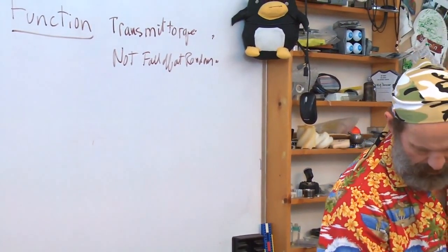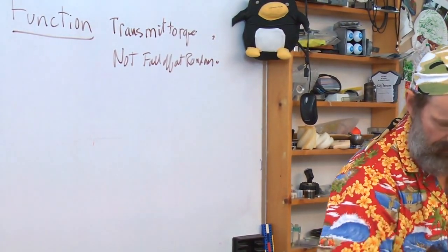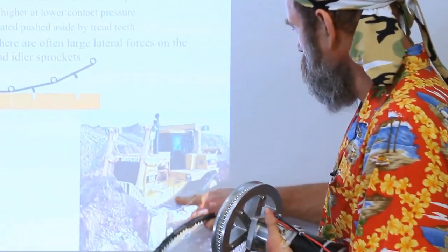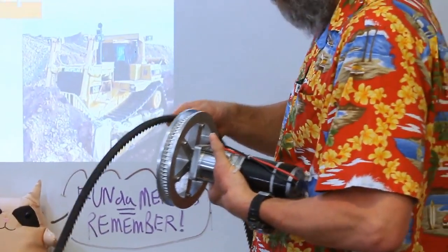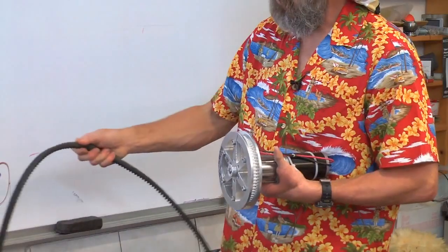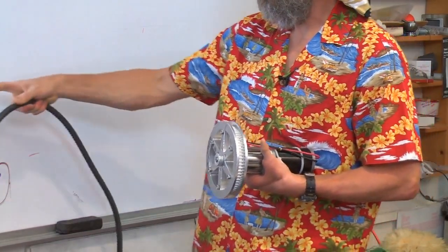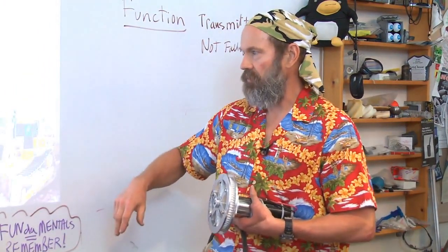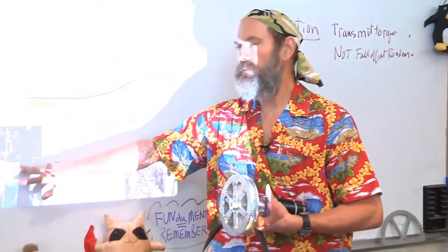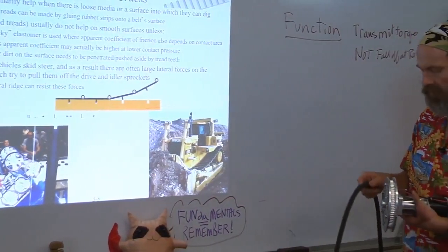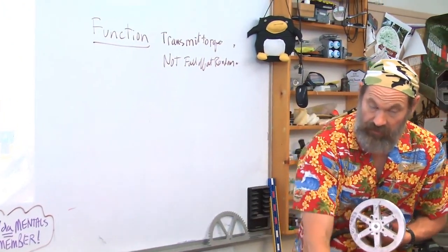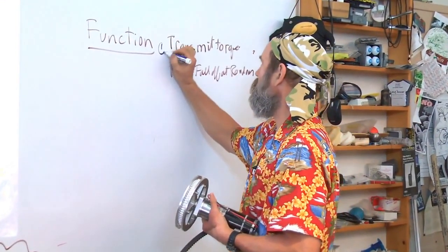Well, transmitting the torque, we're either going to use the Capstan effect. That's hard to get really, really high loads without linear forces without having really high tension, which is very hard on the bearing. So we tend to like to use a toothed type belt or a tooth track. And on a belt that may have high side loads because you just can't avoid them, for example, in a bulldozer application or in some of these design contests where people like to use tracks, we're going to split these two functions into each having a specific design parameter, one for each function. We'll call this 1, 2.